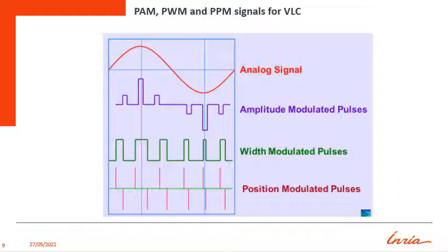In our work, we don't use all three modulations, but we just use PAM, pulse amplitude modulation, with different indexes, so 2, 4, 8, and 16 PAM, and pulse position modulation, so 2, 4, 8, and 16 pulse position modulation. In this way, we can show a faster communication, mainly with a PAM with a high index, or a communication which is more robust when there is more noise.